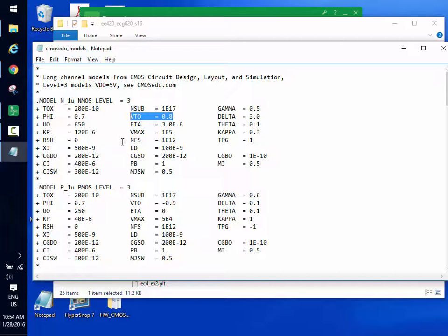And remember also, threshold voltage isn't where you go from zero current to having some current. If you look at the curve, it's rounded, and you still have a little bit of current flowing in there. And I'll talk about that, I hope, when we talk about the sub-threshold slope.